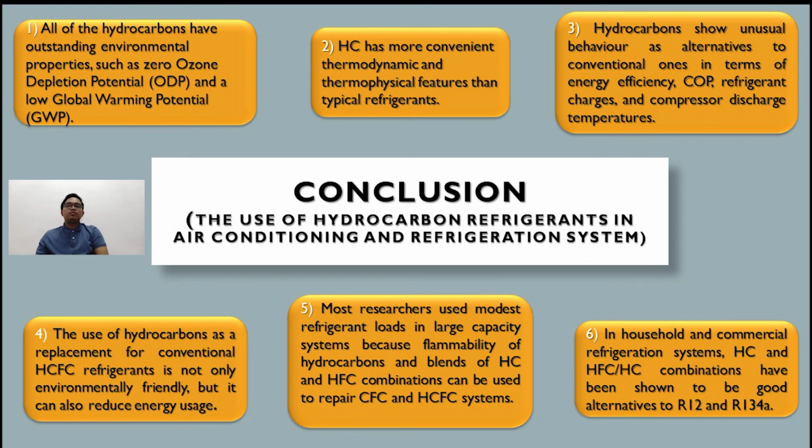Okay, the conclusion for this topic, which is the use of hydrocarbon refrigerant in air conditioning and refrigeration systems, is that from the thermodynamic, thermophysical and heat transfer perspective, a number of hydrocarbons are acceptable as refrigerant. All hydrocarbons have excellent environmental characteristics such as zero ozone depletion potential (ODP) and a low global warming potential (GWP).